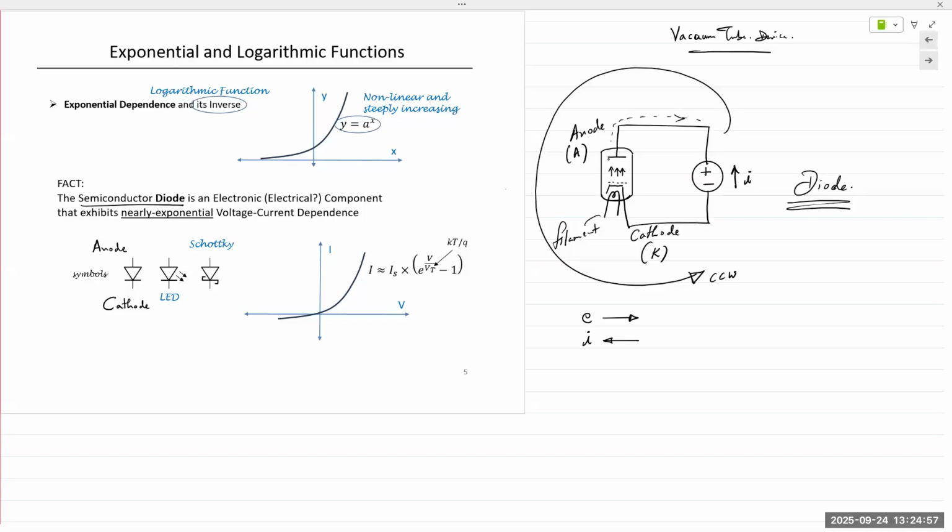Electrons and holes are something that you'll learn in semiconductor theory in EE 315. Essentially, just in short, I'll explain. When an electron moves out of its spot from an atom, it leaves behind an ionized atom, right? But when an electron moves out, what is left in the actual spot where the electron was? An empty space, an empty spot. For lack of a better term, scientists and researchers agreed to call it a hole, H-O-L-E. It's an empty spot, it's a hole.